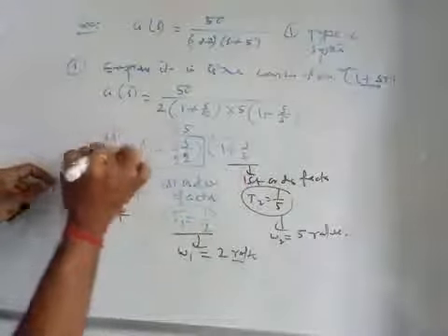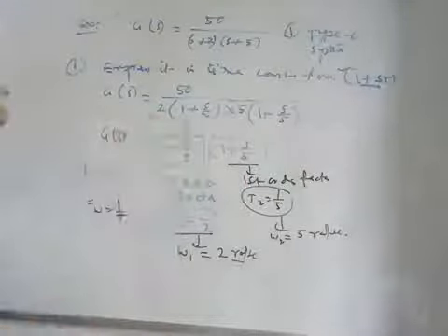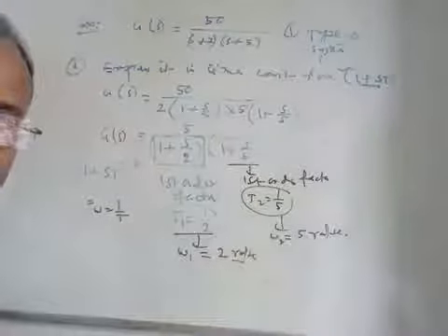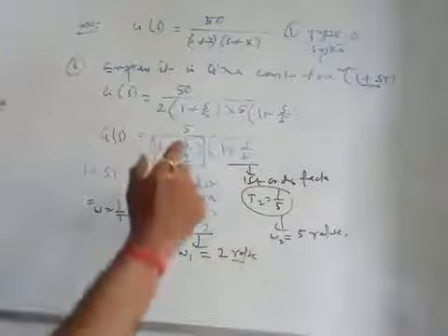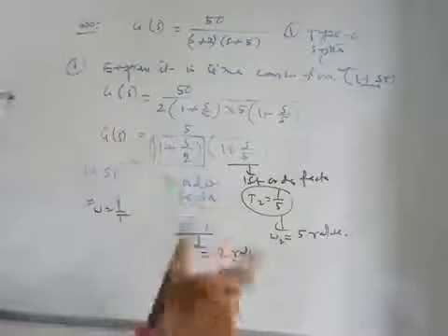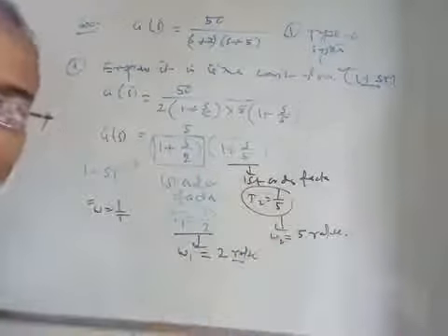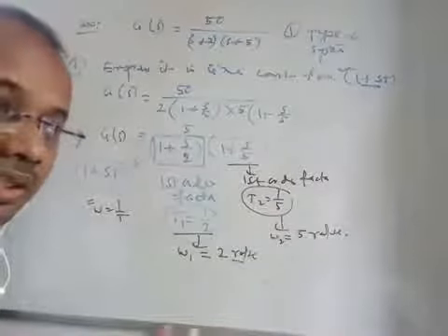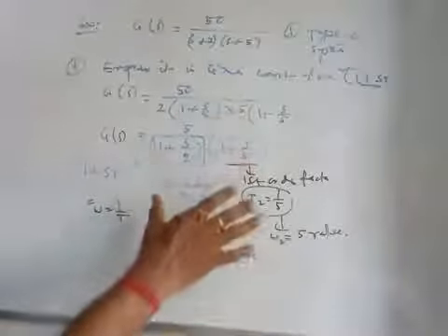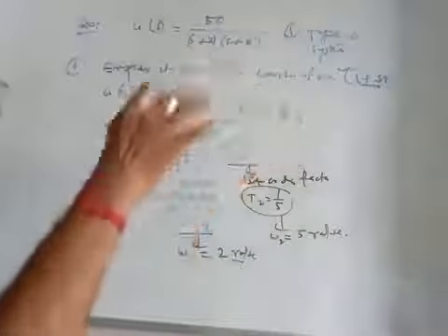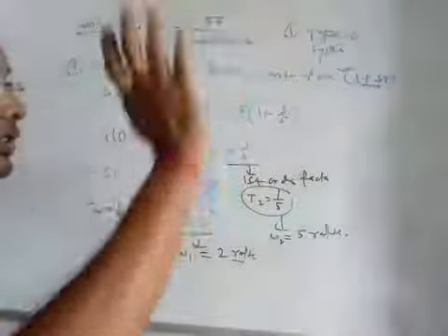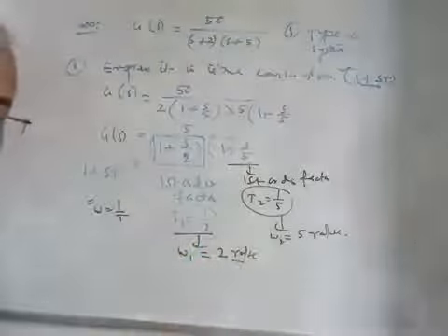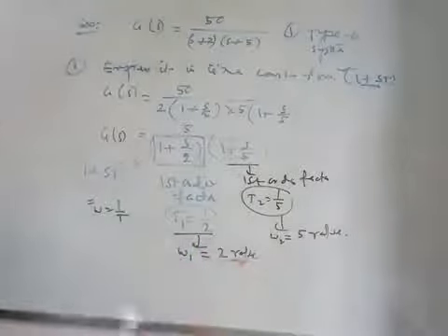That means G(s) in time constant form is expressed like this, and corresponding to each factor we are going to get the corner frequencies, right? If there is any factor which cannot be expressed in time constant form, the corner frequency is not available for that, so corner frequency calculation is not possible. So till now what we have come to know is the time constant form is like this, and corresponding to that, the factors give us the corner frequencies, right?